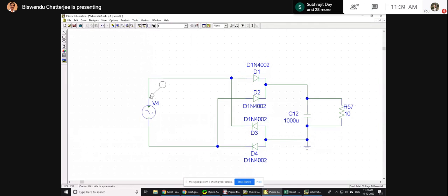The first one you place will be the plus sign, and the other will be the minus sign. For DC it matters, and for AC the phase will matter. No problem. I just want to measure the voltage differential, and I place it across this voltage waveform. Now let us simulate.